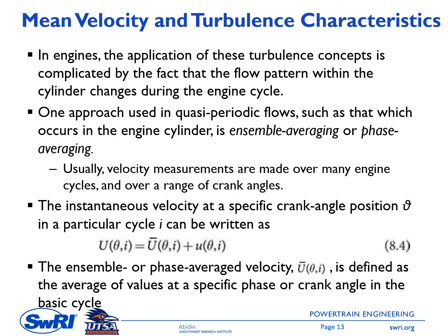In engines, the application of this turbulence concept is complicated by the fact that the flow pattern within the cylinder changes during the engine cycle. So we will have different flow patterns during the intake stroke, during the compression stroke, and during the combustion. We have a very high gas velocity because of the combustion. In case of knocking, we might have a sonic flow there.